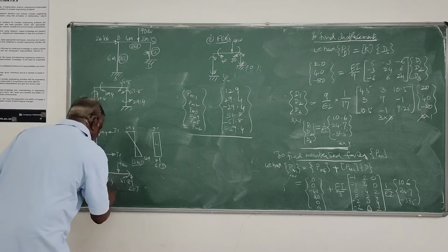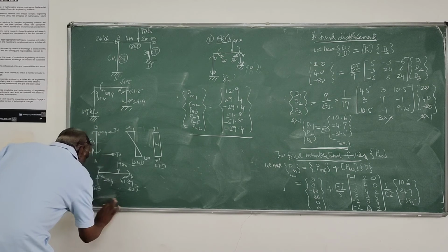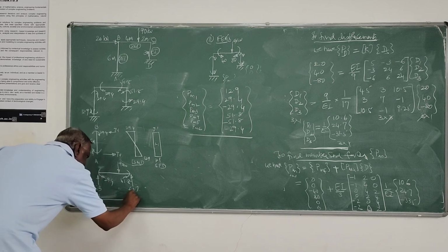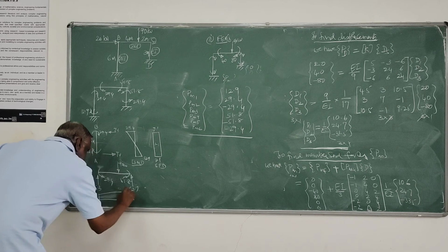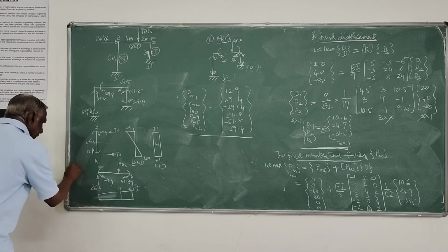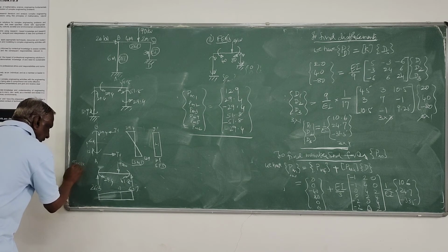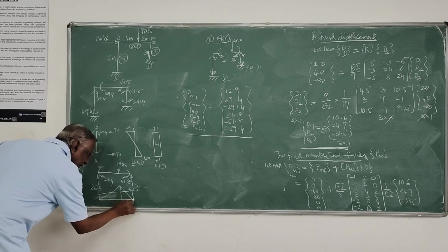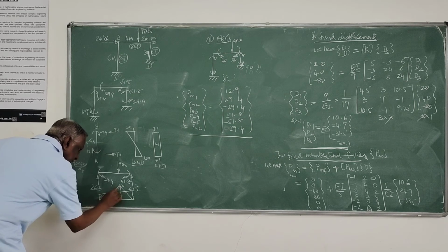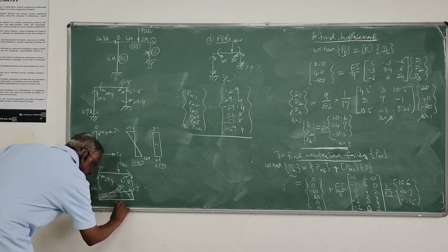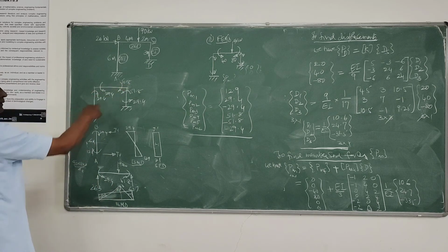So the bending moment diagram for this, you can plot it. Here 29.4, here it is 51.8, join this and this. So that is the fixed moment diagram. Free moment diagram is WAB by N. W is 90, 4 into 2 divided by 6, that is 120. It is definitely more than 63.7. So this is the net moment diagram, negative, positive, negative. This is the net bending moment diagram in BC.